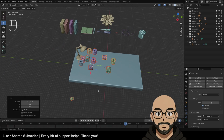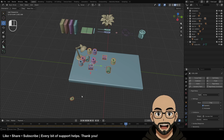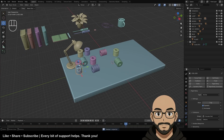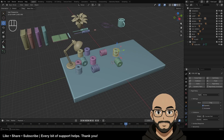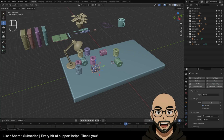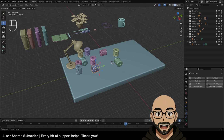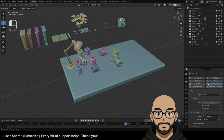That's fine. Now what I want to do is just go object, rigid body, apply transformation, delete that, and then now we can get rid of the rigid body here. So now these should have no rigid body because they're not moving. Now we can position these. I'm just going to remove the rigid body off those. So I'll just kind of use dynamics to just spread them out.